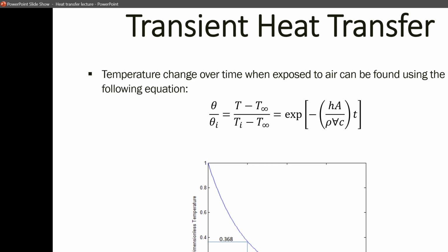We calculate two heat transfer coefficient parameters for the two cases. You have your result for the heat transfer coefficient. But as I said, we are making an assumption here. So we have to investigate the validity of that assumption. This is where the Biot number comes into play.